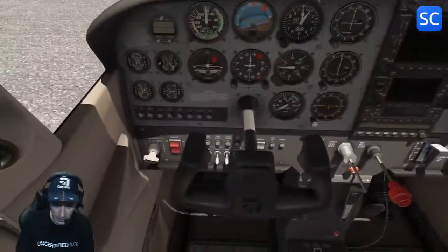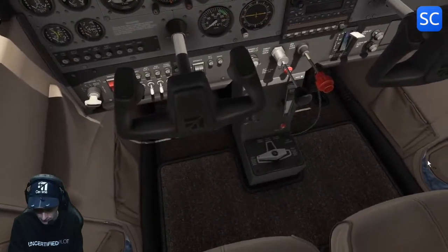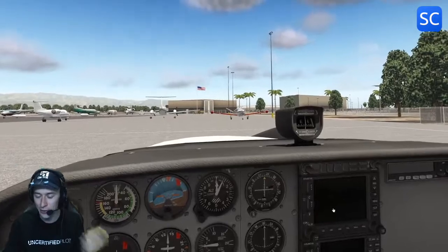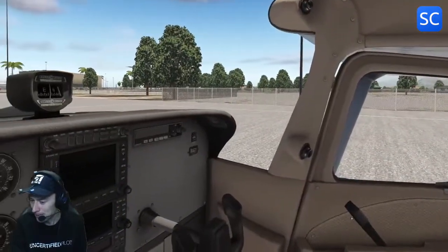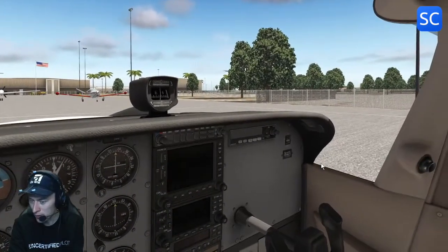First off, the parking brakes. Those are set. Great. Well, live vest we don't need, and fire extinguisher, let's just pretend that's in the green. I usually just go through these checks intellectually because I think those are relevant. Doors closed, ELT set to auto. That's also an important remark.